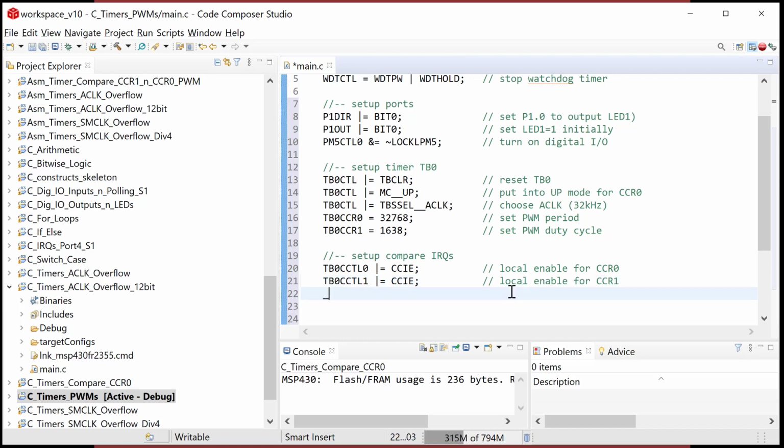And now let's do the global enable. So let's do enable interrupts and turn purple. Come on, buddy. Didn't turn purple. Did I misspell it? __enable_interrupt. Why isn't it purple? Oh, you got to spell it right. Okay, so then we'll do enable maskable interrupts.